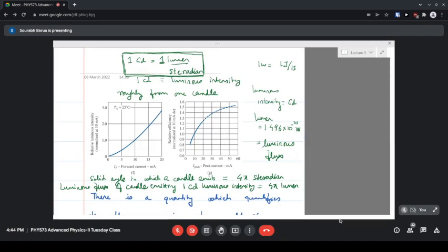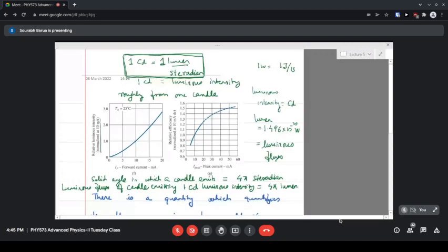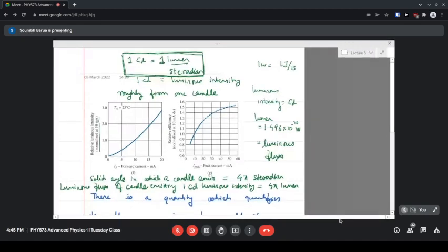Now this luminous intensity, we have added the word relative before that. So it is a relative luminous intensity, not absolute. It is in units of the luminous intensity at 10 milliampere. That is what has been written here. It is normalized at 10 milliampere. So we have values of the luminous intensity for different currents, right? So we have 5, 10, 15, 20.